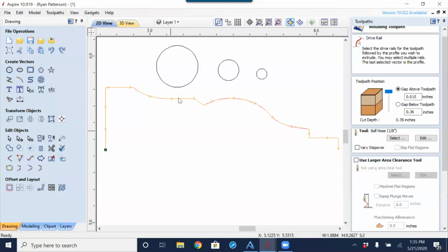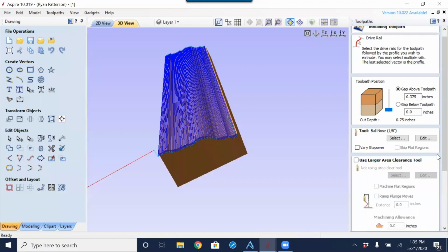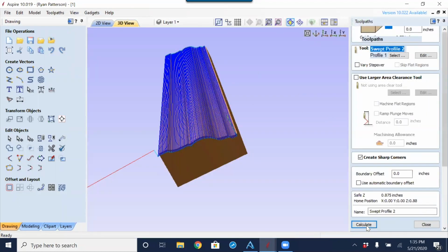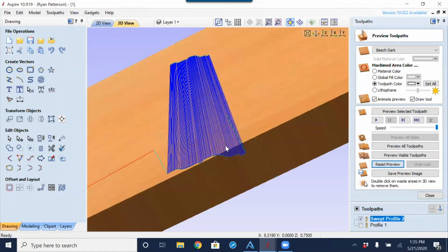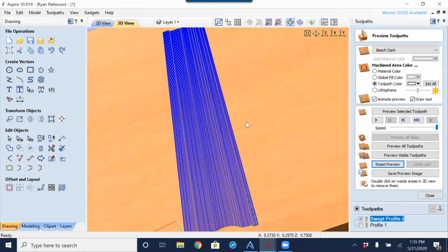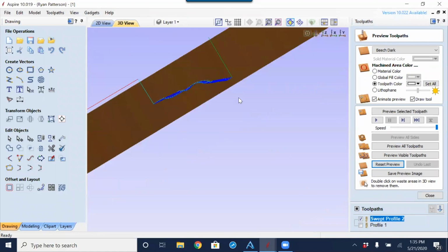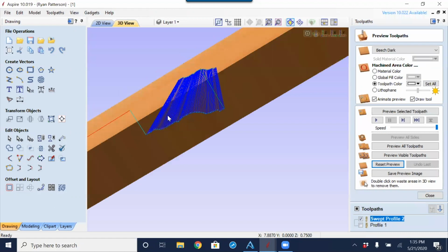Now I talked about roughing. So if we did have this material drop down into the material, that is going to be the case where we might have to rough the material out, even with a 1/4 inch bit. If this was hardwood, that 1/4 inch bit may even have a hard time getting down to that area in a single pass, because that's exactly what's happening, it is making all of this in a single pass.